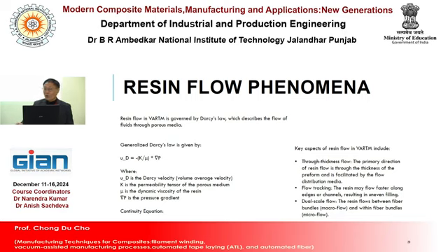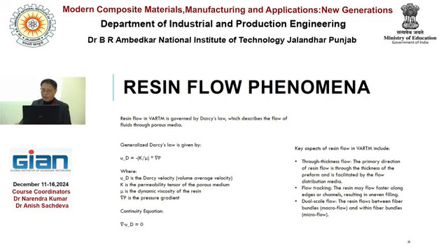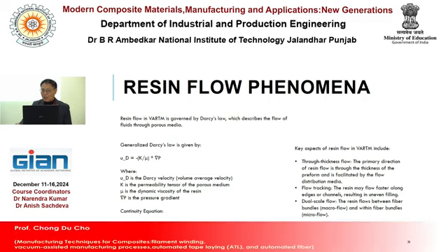One is Darcy's law, a kind of flow in porous medium, and also the continuity equation needs to be considered. In VARTM, from the viewpoint of resin flow, the key aspects are through-thickness flow, flow tracking, and dual-scale flow. These three minor subjects are included.